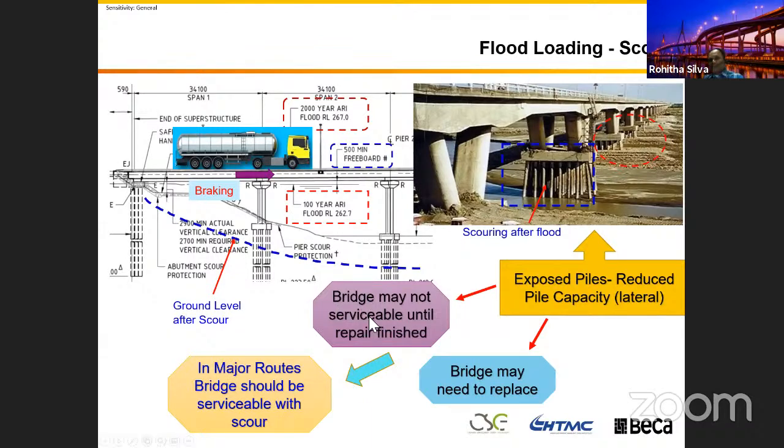And it's important you check your bridge after a flood event, right? Because if you check your bridge after a flood event, you can have traffic, even with controls, as decided by the traffic agency. You don't want to use 100 kilometers per hour normal day-to-day serviceable state. You can just tell them, okay, we can let you use this particular bridge, but you can't drive 100 kilometers per hour, you just drive 40 kilometers per hour. Still, we can let you use the bridge. You can have controls, but still it should be usable.